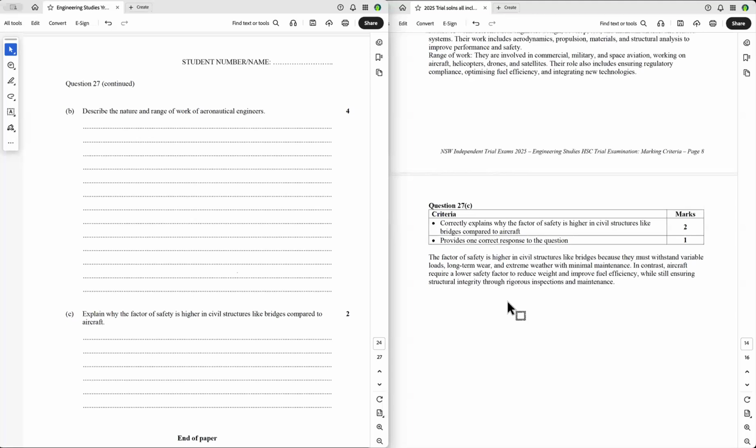And so there's more confidence in the materials of an aircraft so that you can reduce the factor of safety. And the other reason is that the lighter the plane, the more payload and the more money that the plane can earn. So it's imperative that airlines have a low factor of safety to keep costs low and safety high.